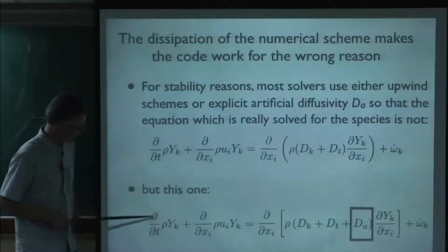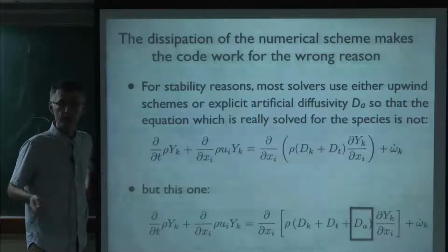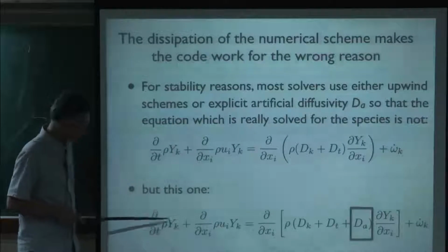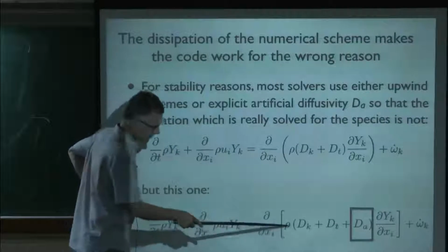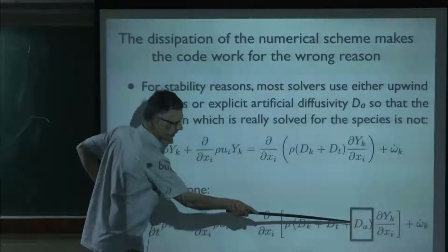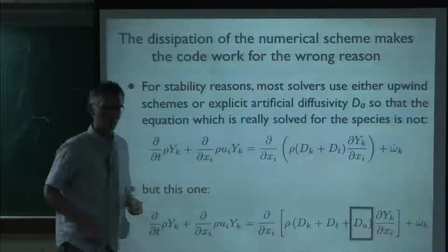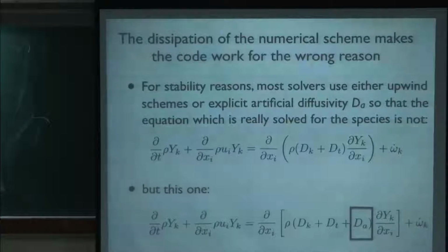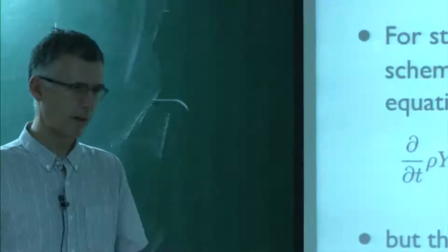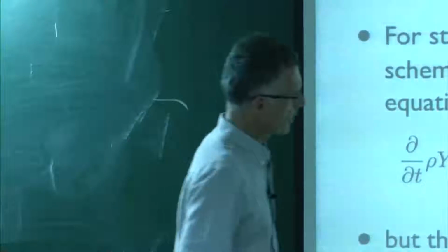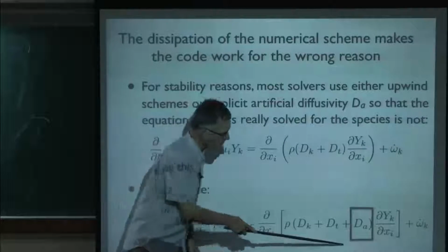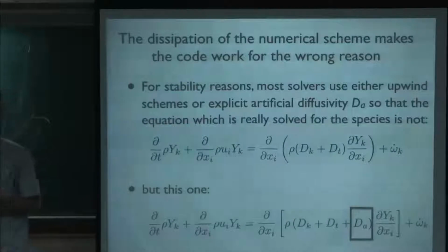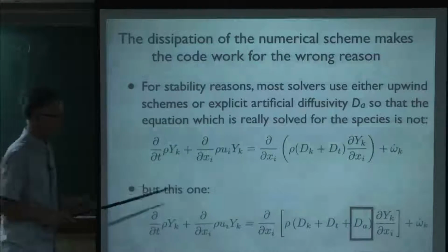In all of these codes, typically Converge, for example, the equation which is really solved is this one with a turbulent diffusion. And here there's something I will describe tomorrow, which is an artificial viscosity due to the scheme itself, because of time advancement, because of space advancement. Now, this really means that the viscosity which is there in the code is much larger than the normal viscosity.